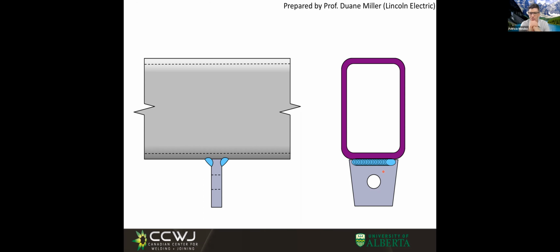Not uniform, not uniform. Where is the stress concentration going to be? Beginning and end or middle? What is going to be having the highest loads? The ends or the middle? The ends, absolutely. We put the load, resist on the sides, and because this part is stiffer than this part in the middle, we go with a stress concentration at the ends.